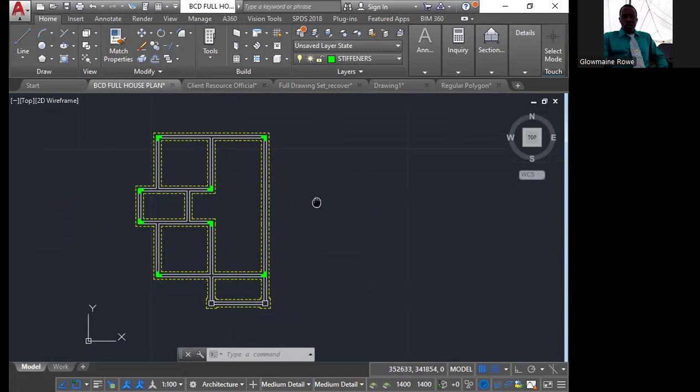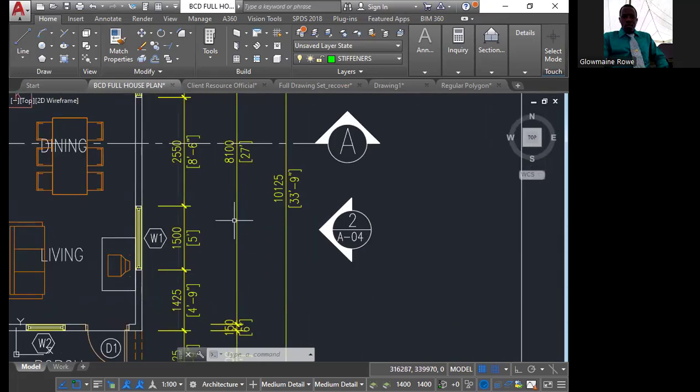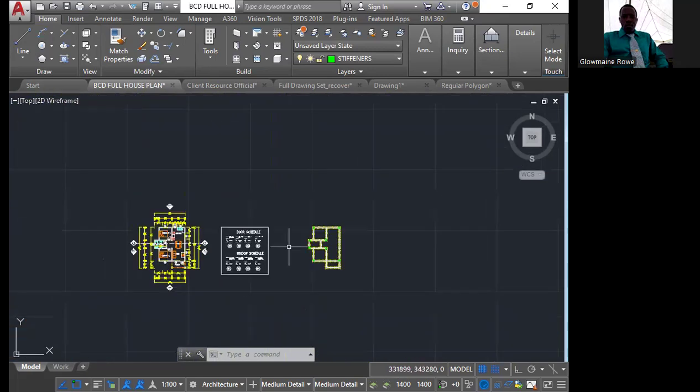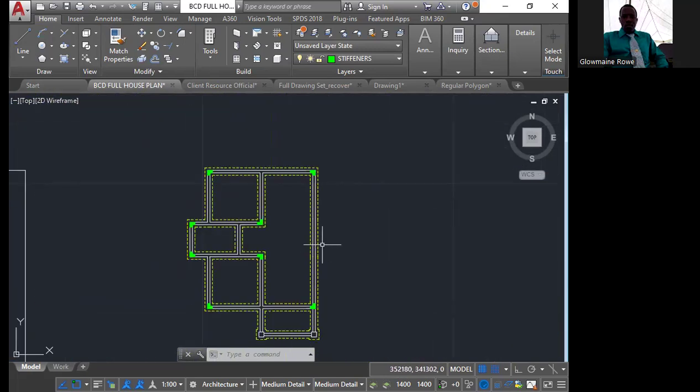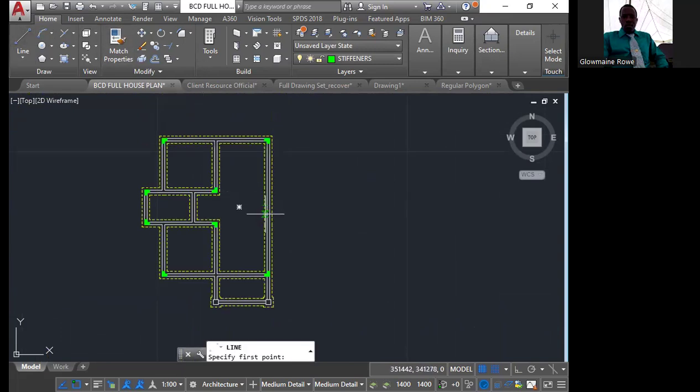All right, so the span of this wall more than likely is longer than 20 feet. All right, so the span of this wall is 27. And we say that wherever we have a straight span of wall that is 20 feet or more, you're going to need a stiffener. So we're going to make an I stiffener. Select line command.